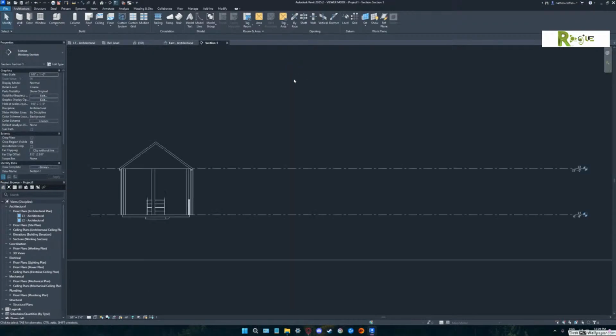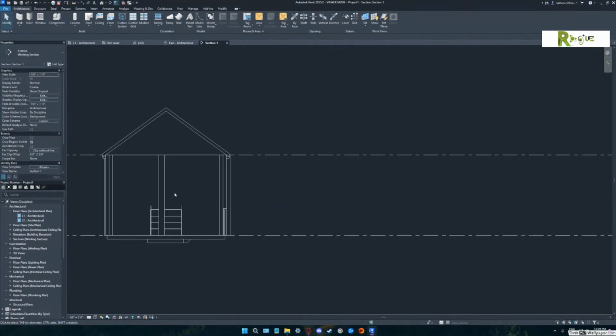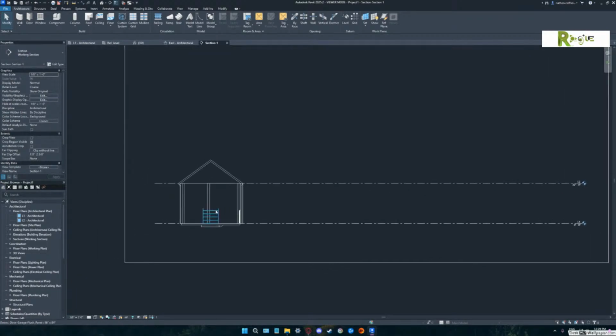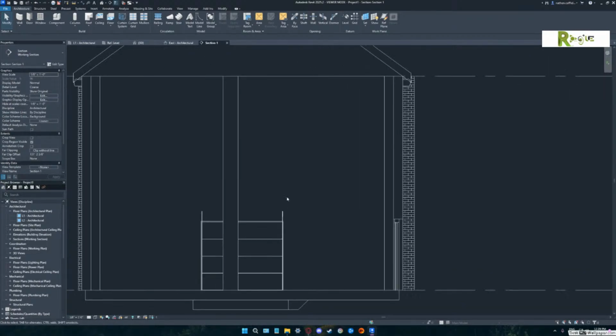Double click, I'm sorry. Right? Okay. And see, that's the section of that building. If you zoomed in, you'd say the section doesn't look too good. Zoom into that area where you were. The section doesn't look too good, and the reason being is you're in coarse mode. So put yourself in a medium or a fine mode. You're doing great, man. Now all of a sudden it makes a little more sense.